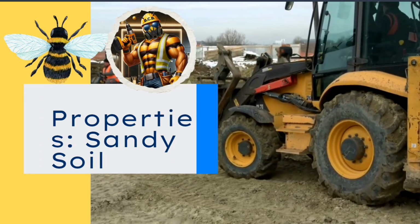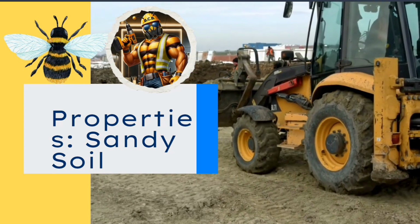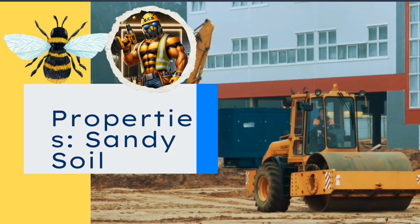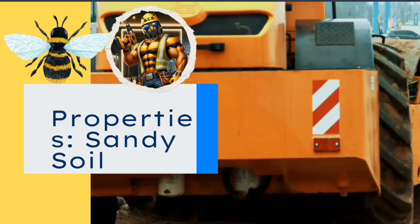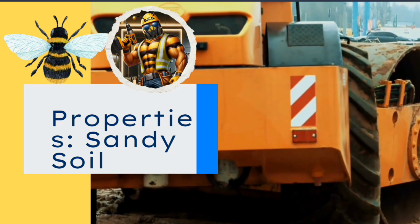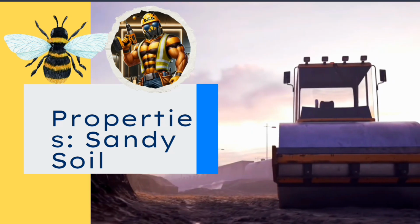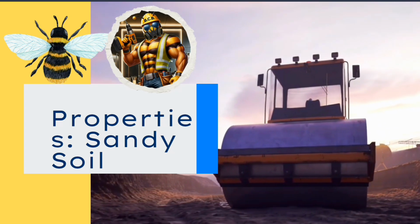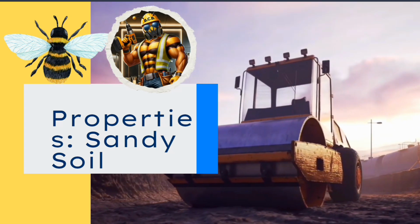Next, let's talk about sandy soil. Unlike clay, sandy soil has coarse particles with low cohesion, meaning it doesn't hold together as well. But here's the good news: high drainage capacity. Sandy soil allows water to flow through easily, which reduces the risk of water-related foundation issues. Because of this, sandy soil is often considered a good option for foundation support as long as it's properly compacted. Without compaction, sandy soil is prone to settling over time, which can cause problems for the structure.